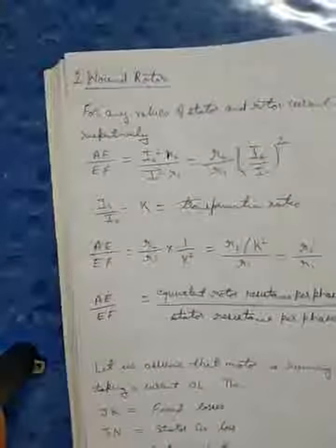Now finally we get R2 dash upon R1, and it is the ratio of equivalent rotor resistance per phase to stator resistance per phase. Now let us assume that the motor is running and taking a current OL. Then, from this circle diagram,